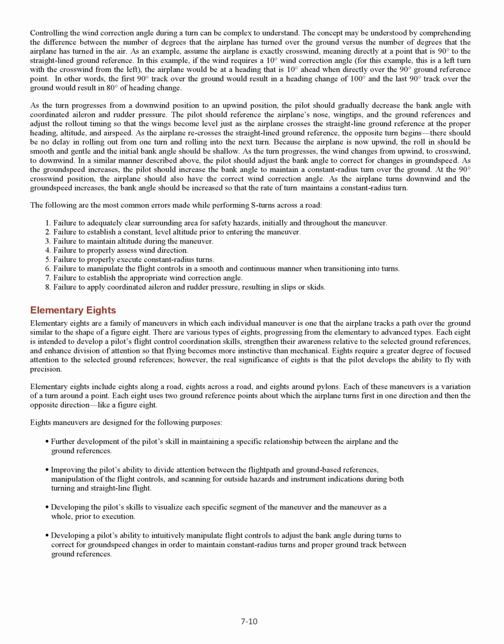Elementary eights. Elementary eights are a family of maneuvers in which each individual maneuver is one that the airplane tracks a path over the ground similar to the shape of a figure eight. There are various types of eights, progressing from the elementary to advanced types. Each eight is intended to develop a pilot's flight control coordination skills, strengthen their awareness relative to the selected ground references, and enhance division of attention so that flying becomes more instinctive and mechanical.